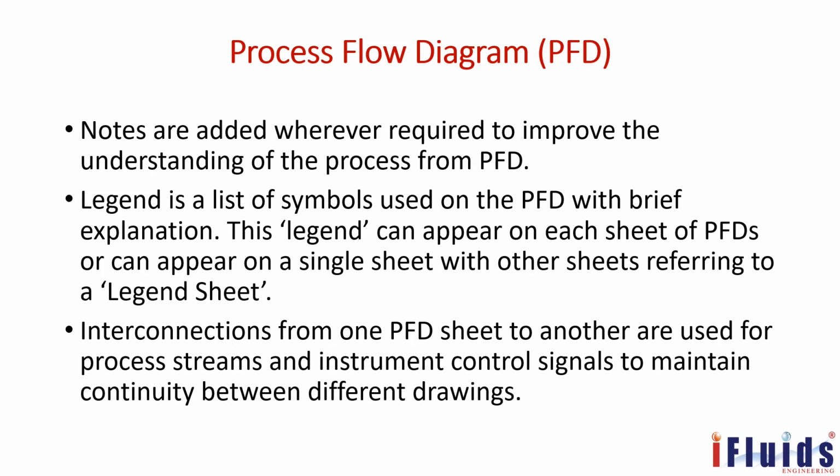Interconnections from one PFD sheet to another are used for process streams and instrument control signals to maintain continuity between different drawings. In case there are 2-3 PFDs, if a stream is going from one PFD to another PFD, you have to show the interconnection from and to.